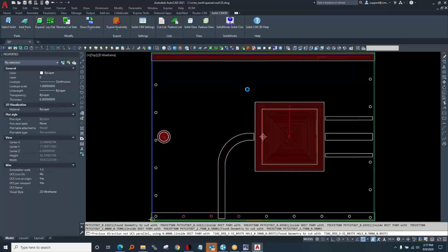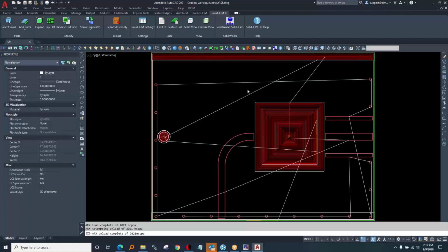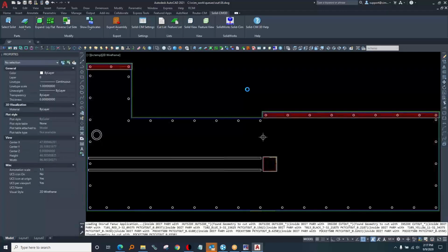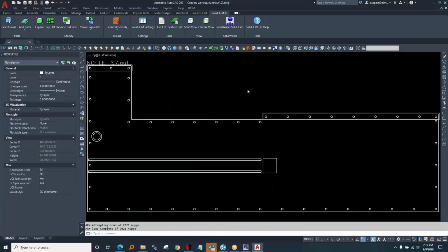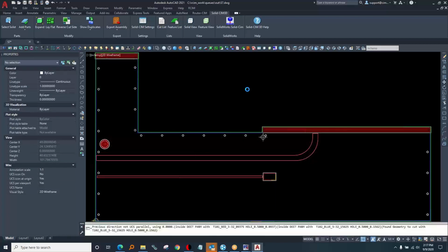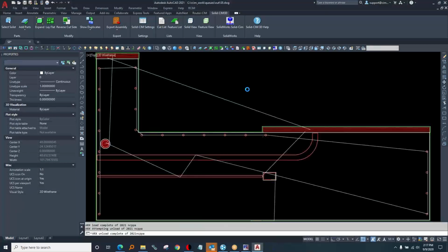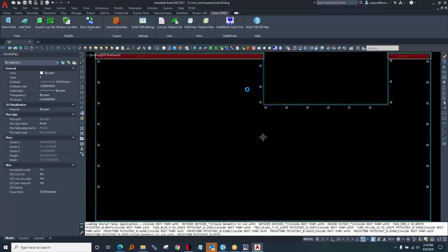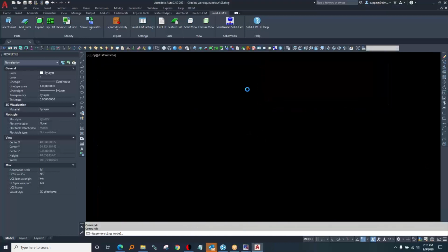A lot of these parts have machining on both sides. So we're going to do what's called two-sided nesting, where you'll put the sheet on the table upside down. It'll do all the marking and the machining for the back side. It trims the edge of the sheet, so when you flip it over, it's a machined edge that matches up the parts again. And then it'll do the front side operation. So a single sheet could have up to 4 programs on it: a marking for the front, a marking for the back, and machining for the front, and machining for the back.